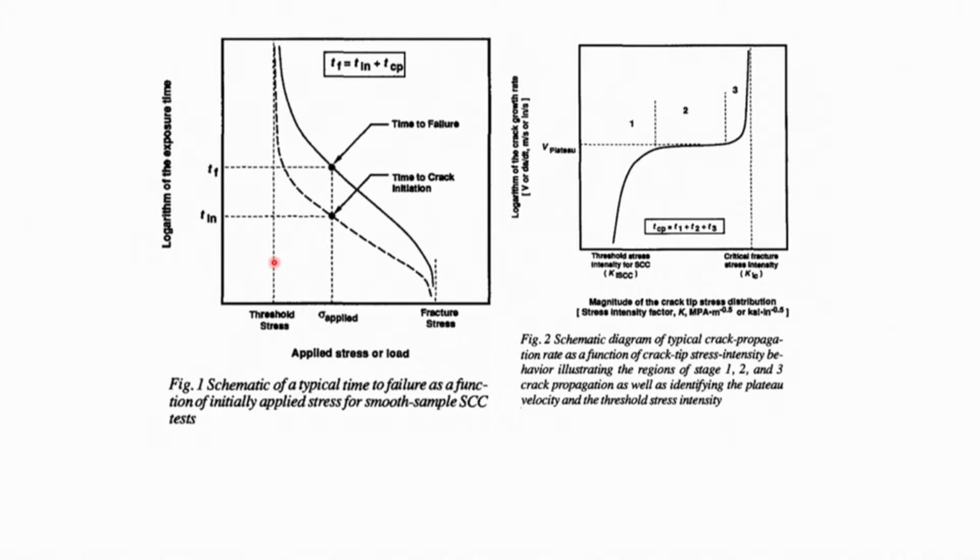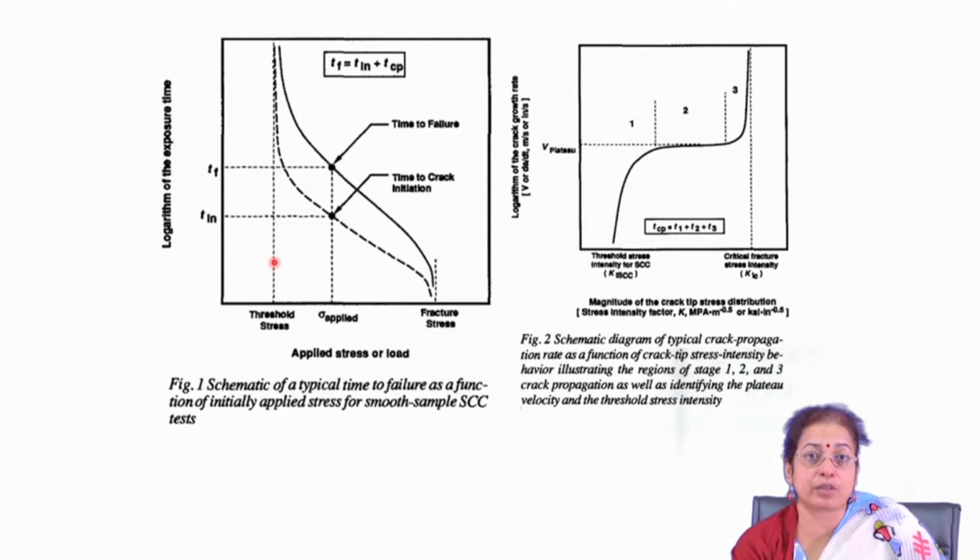So, the stress corrosion cracking diagram, or mapping, is very important for a specific alloy system in a specific environment, for choosing the alloy for that particular environment. But you have to understand that this threshold stress can be much lower than the UTS or sometimes the yield strength of the material. So, usually the component fails under stress in a corrosive environment, when it undergoes stress corrosion cracking, at a stress much lower than the yield strength of the material. So, you cannot really predict the stress corrosion cracking behavior, or design the component, based on its behavior in a simple environment where there is no corrosive fluid.